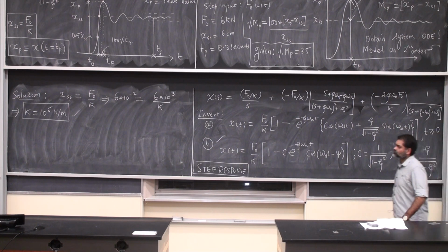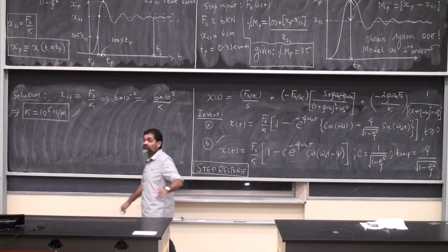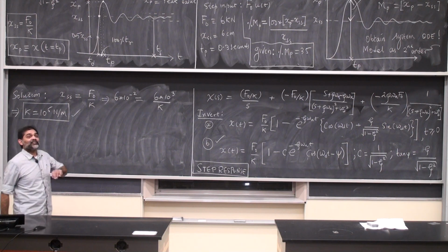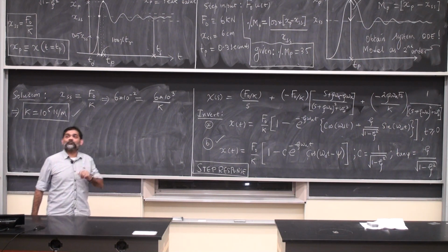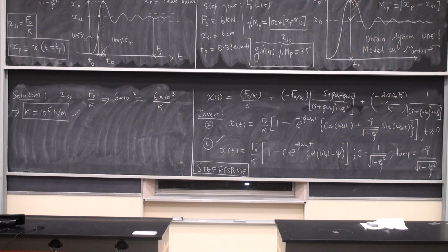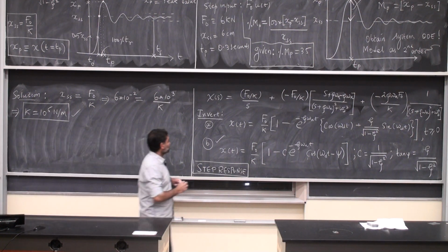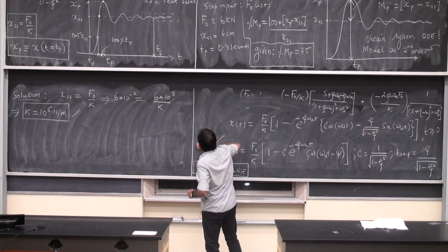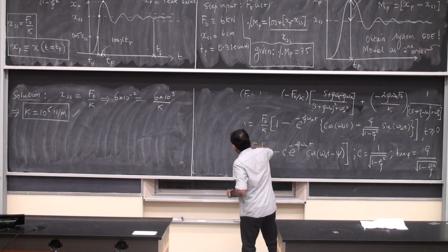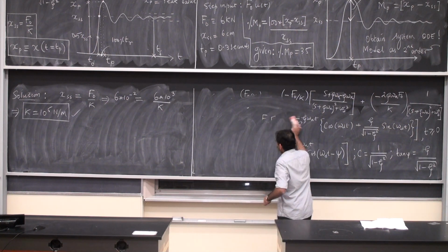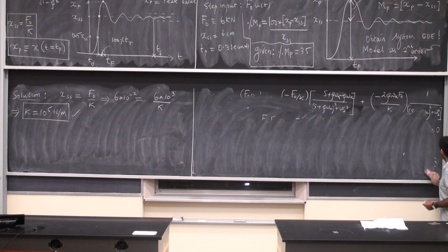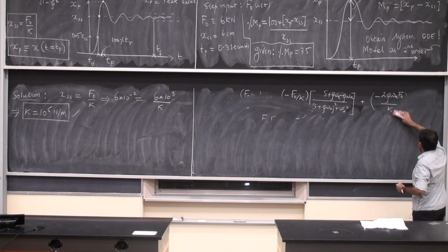How do I get the other two? What are the other two parameters? Mass and damping constant. If I can find the damping ratio and the natural frequency, I can get the other two parameters. So that's what we're going to do next. But before that, I'm going to erase this particular panel here, and I'm going to ask you a question. Look at the plot that I have. Can you think of any special occurrences at the peak point? What's happening at the peak point?